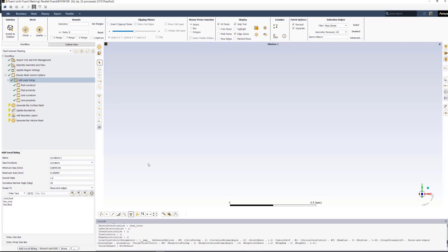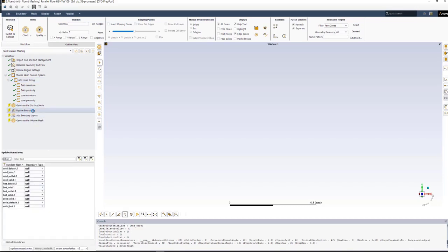Now, as you get comfortable with working in Fluent and these steps, generally what I'll do is rather than going to surface mesh, waiting and coming and defining everything else, we can ahead of time prep the volume mesher. So under cold inlet, we'll select mass flow inlet. We'll go ahead and define the outlet and inlet for the other two as well.